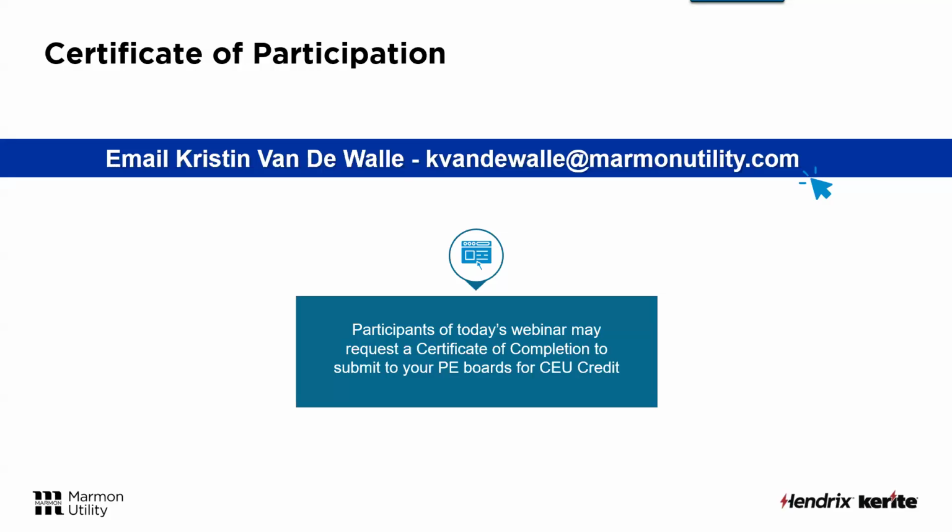Thank you, Ted. Next question is, if a utility wants to extend an existing installation of Hendrix from where it transitions to bare wire, would they simply splice the two runs of Hendrix together, or is the system designed to be continuous with no splices along the way? Well, like any overhead system, we try to minimize the number of splices. But obviously that could get pretty expensive, especially if you've got a bunch of existing spacer cable and then you want to extend it.